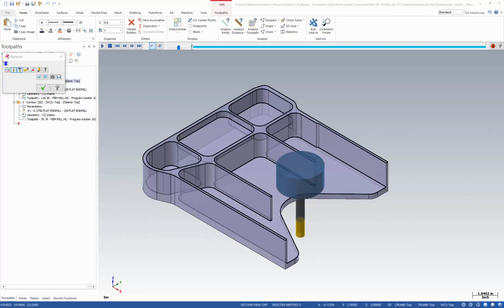Then again, the tool will take another Z depth increment and perform the first 2 roughing passes. Move up in between the 2 depth of cuts, will create a finish pass, and then goes back to the second depth of cut and makes the finish at that Z level. And we'll continue like this for the last depth of cut. Let's see it in back plot.